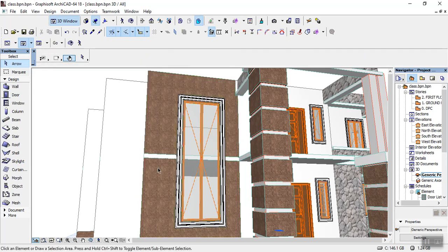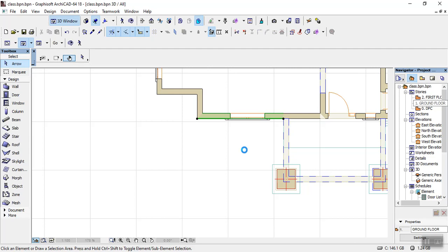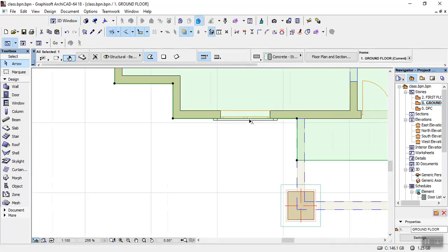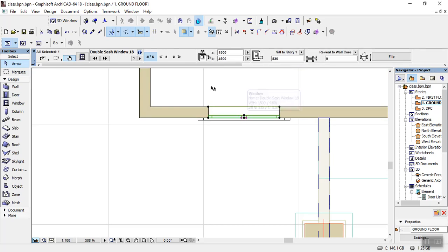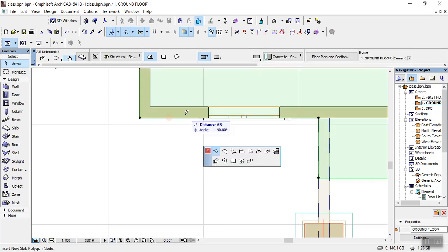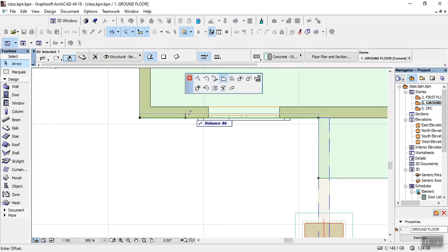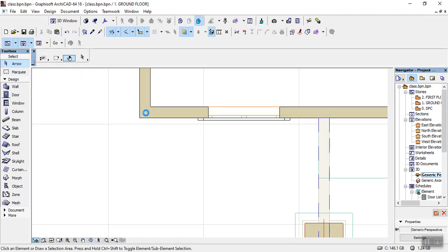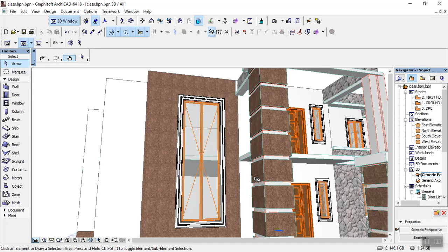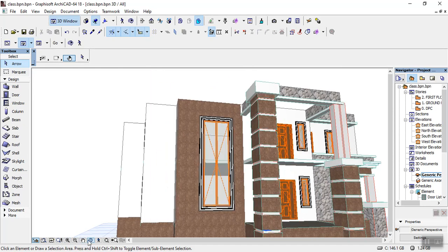Then if you see very well, there is a white background here. This is the slab thickness. And it's reflecting. So for it not to reflect, I'll come down to the spot. I'll pick the slab. I'm going to offset this backward a bit, just a little bit. Okay, let's see. Always follow the process. Perfect. So you can see we got this done.